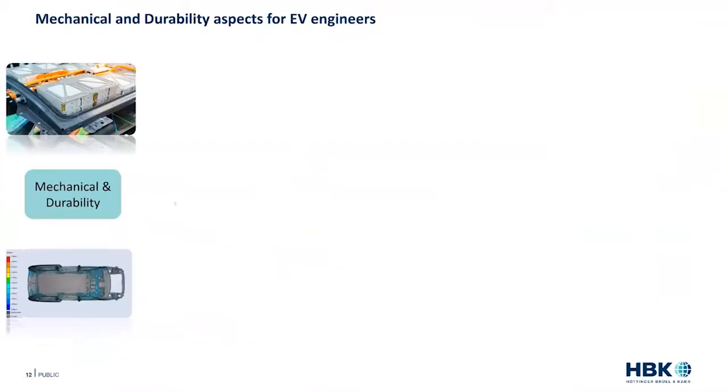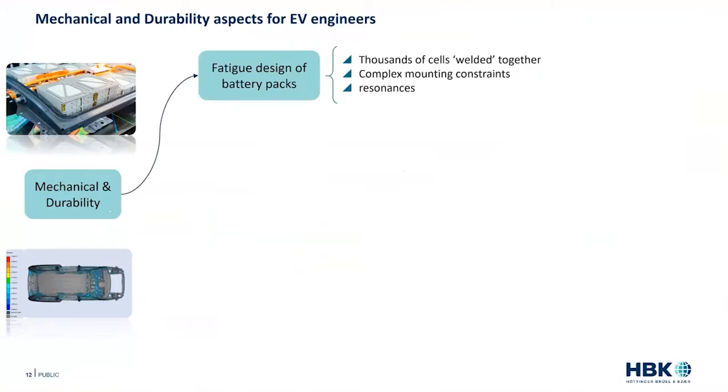So you can view it from different perspectives. First, if we're talking about the battery packs, we can look at the vibration-induced fatigue. There are thousands of cells. They're grouped in modules, and those are grouped together to constitute the battery pack. And those cells are often welded together, and those welds suffer from vibration fatigue.